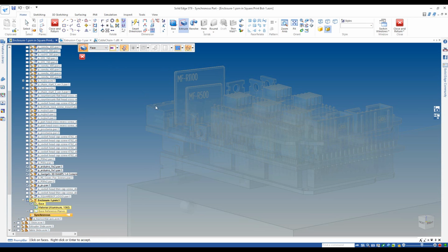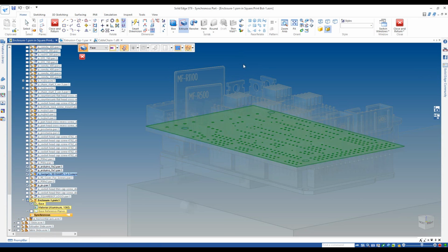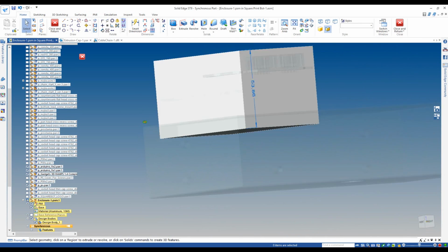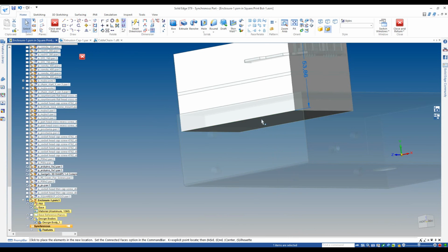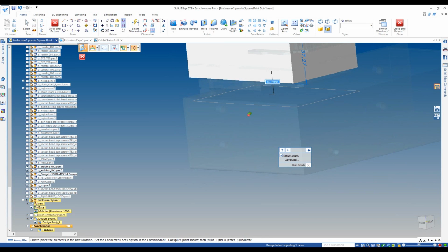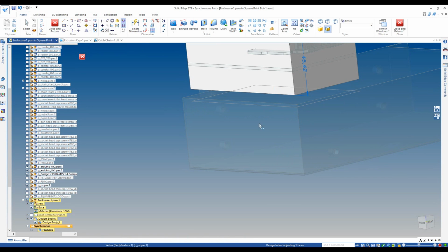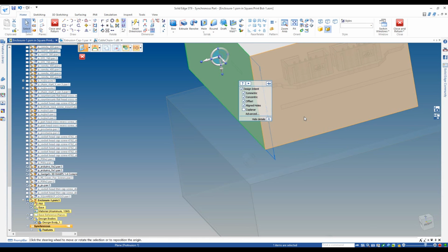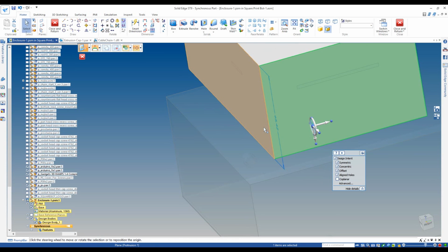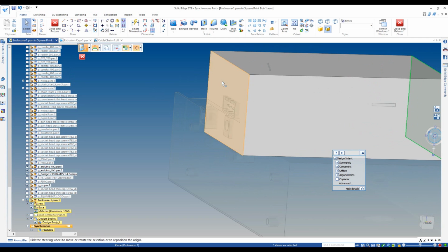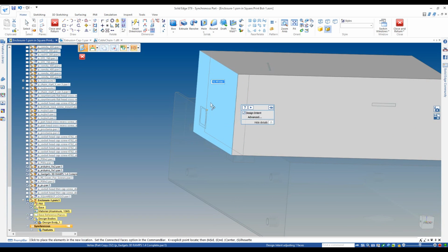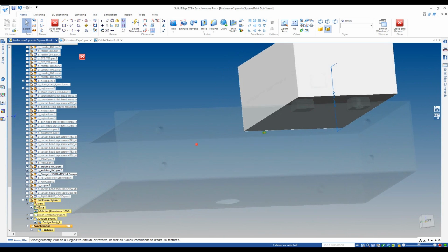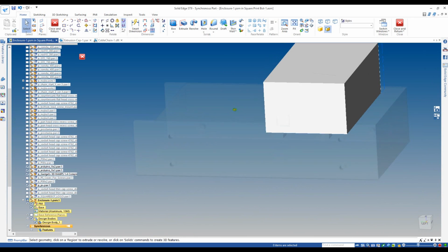Basically, I want to be able to enclose an entire body. So I'm just going to create very, very quickly and easily the body that I want to enclose. Just move the bottom up a little bit, and I'll actually just snap that onto the edge of the bottom enclosure. That's correct. No, I'll just bring that out to enclose the circuit board. Bring this one out to enclose that part of the circuit board. That looks good. I might need to just bring it a little bit further out this way. So it now completely encloses the circuit board. And there's a couple of those foot mounts poking out the bottom. That's okay. That is about the size that I want it.